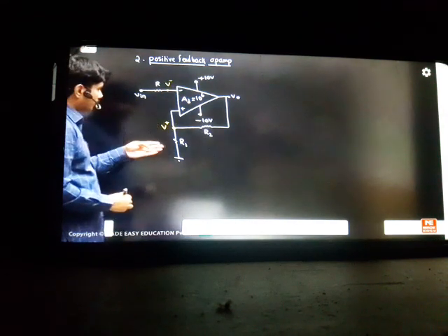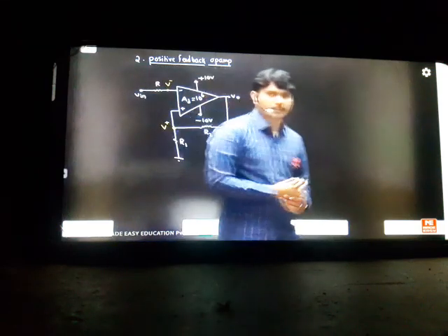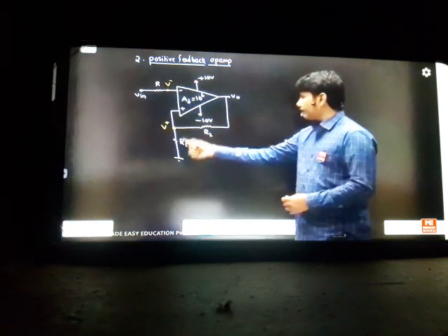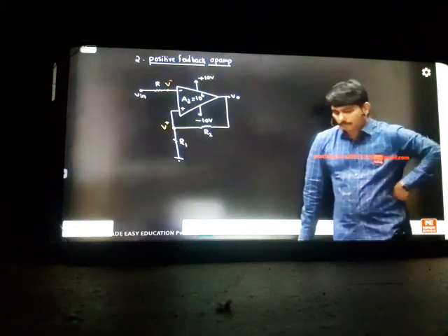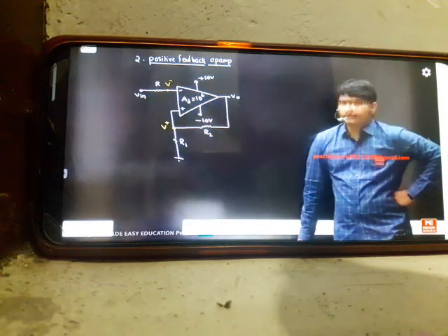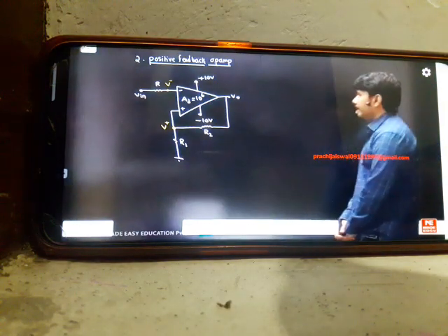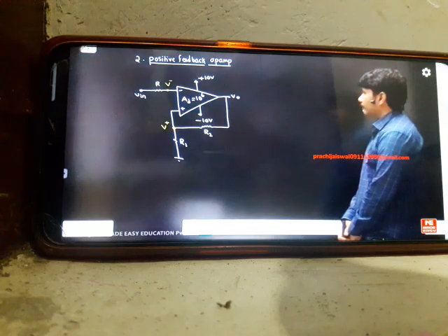Now, can you see that here my investigation will start again. What is V plus here? I'm interested to know what V plus is, and I want to know what V minus is. Some students can think, sir, R1 purely creates some positive potential here. For V plus, I need some potential. That potential may come due to this current flow; some drop will come, and that will become V plus. Previously V plus was ground, we had taken. Now you can get some quantity there at V plus. Let us start thinking about what your V plus and your output are.